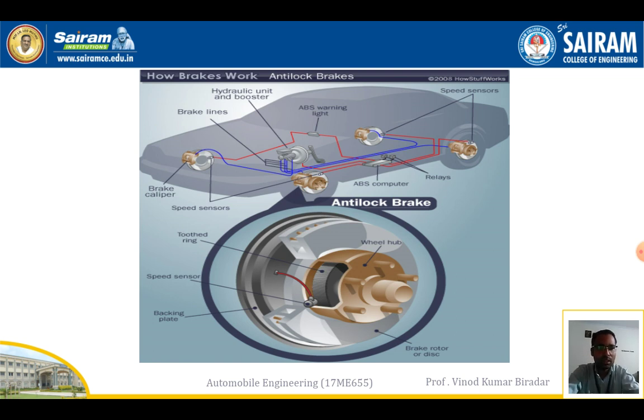The hydraulic part I already explained, but I will repeat. When a driver applies the pedal, the master cylinder will actuate. From the master cylinder the fluid will flow to the wheel brake. As the rotor disc rotates, the sensor will indicate that it should lock the system.